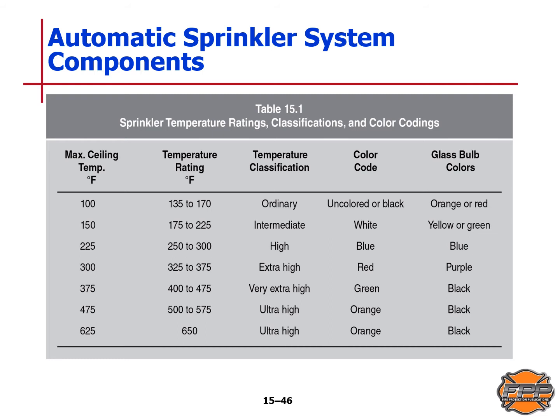This slide shows you the automatic sprinkler system components. This is table 15.1 from your text, and it shows sprinkler temperature ratings, classifications, and color codings. These are all things that you should become familiar with.